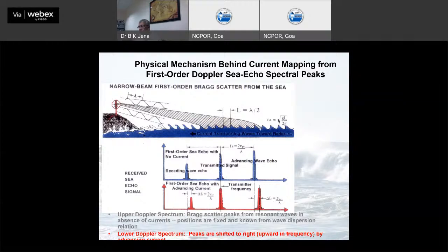Based on this shift, using the Doppler shift, we calculate the current speed and direction, from which place it is coming back, their bearing and the patch bearing. All these things are measured accurately because our RX antenna and TX antenna are geocoded with latitude and longitude accurately.